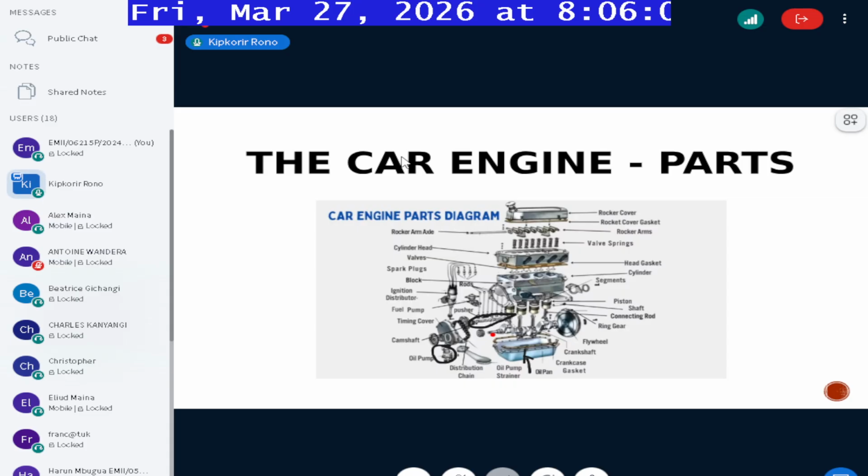So the crankshaft will rotate the camshafts, and the camshafts will operate the mechanical pump. Now that pump will pressurize the oil, so the oil will start moving. That's why it's usually advisable that once you switch on your car, especially from a cold start, especially if you had parked the car at night and it's very early in the morning, it's usually good to allow the car to run for a few seconds. Could be up to a minute or two, for two reasons.